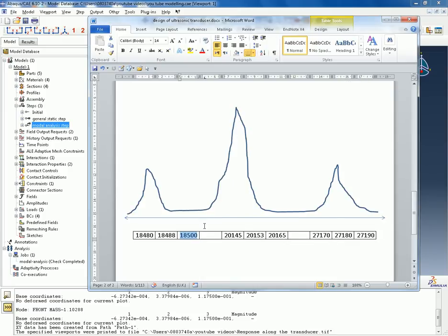So starting from the first point, from the first range, and the upper, where I'll select 20 points, and the bias is the part that shows me how I can specify whether the points of calculation are equally distributed over this frequency range, or distributed more heavily on the sides of the range.